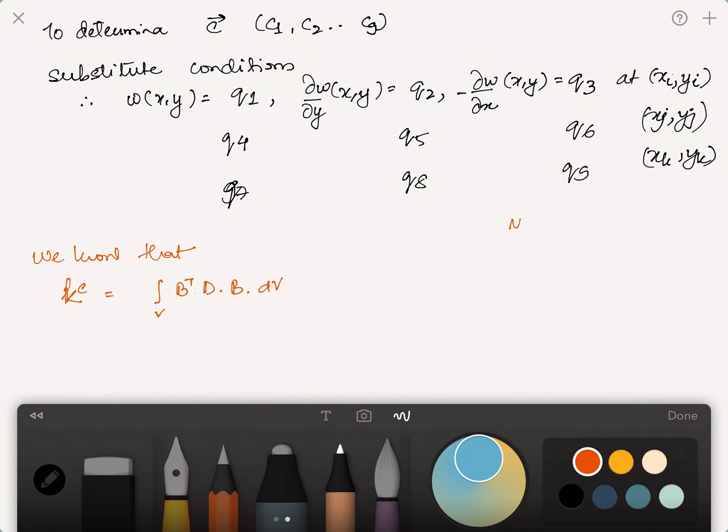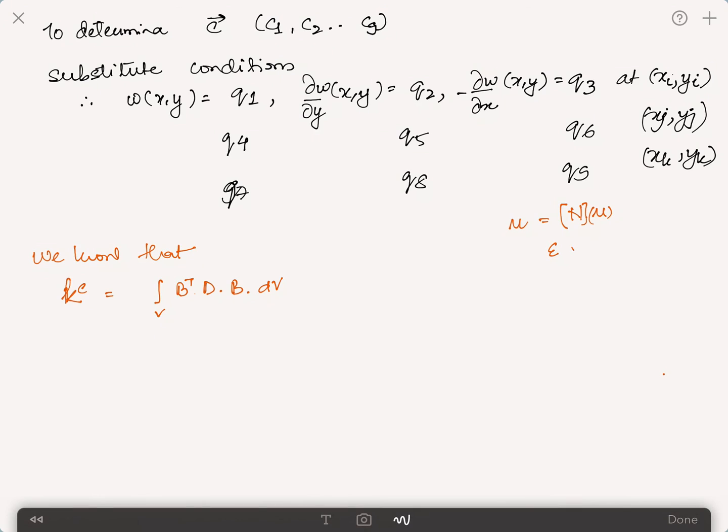So in general, your u vector will be equal to the shape function times u. So we have the shape functions, we'll be able to do a derivative and get the strains out of it, because we also know how to now describe epsilon xx, epsilon yy and epsilon xy that we need for our relation. We'll be able to substitute it back and get to this value finally.